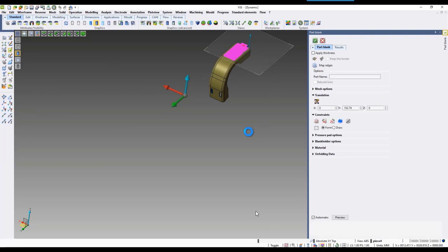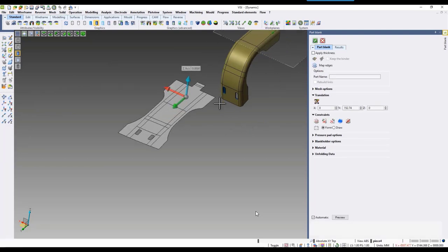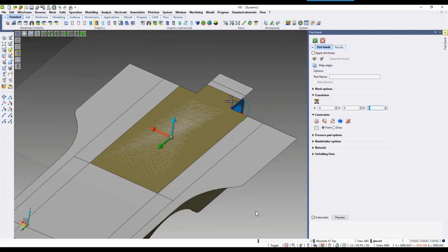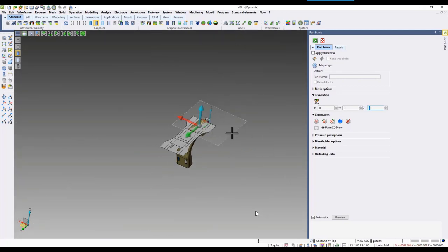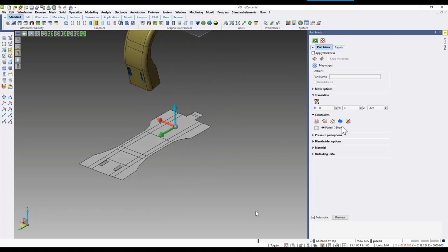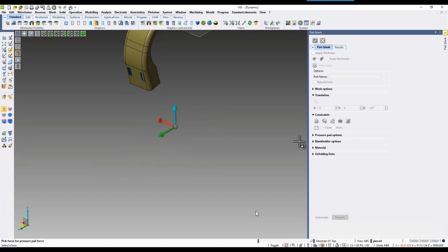So if we select face here, that's exactly what it's constrained to, and that's where it's going to determine its orientation from as well. You can type in your values for the X, Y, Z locations too. As you can see, you can adjust your Z value and wherever you're moving this to. And then you can also reset the constraints, so basically reloading the constraints.